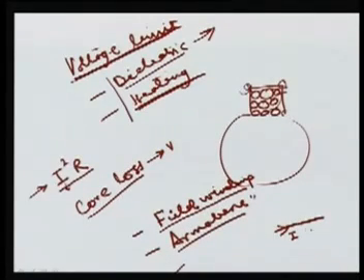Here, the loss in this winding, if R is the resistance, is I squared R, and this power is converted into heat. So heat is continuously dissipated from this conductor, and the temperature of the body is maintained at a particular value. But if the heat generated is not taken away, the temperature will keep rising, and this excessive temperature of the wire may lead to several problems.